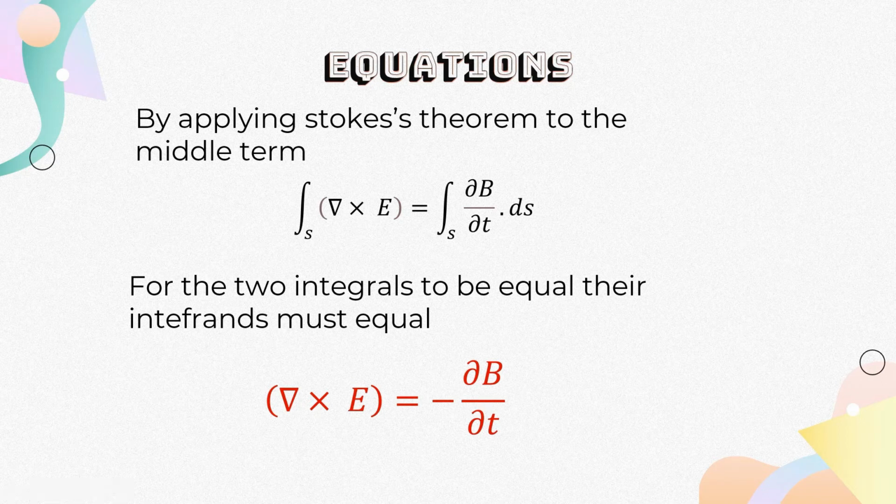These two terms must be equal to each other. This is one of the Maxwell equations for the time-varying field. It shows that the time-varying E field is not conservative, which means that curl E cannot equal 0. This does not imply that the principle of energy is broken or violated, but the work done in taking a charge in a closed path in a time-varying electric field.